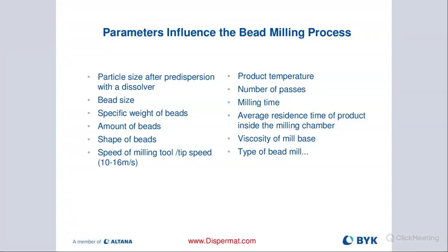So you start out with 1 to 1.2 millimeter beads, mill for an hour, an hour and a half, 2 hours. When you're looking at the results and you see, okay, the last half hour, we're really not getting any more particle size reduction, at that point you want to change out the bead size, go smaller, so that you are targeting the right particle size, and then you run another milling cycle. So that really can add up depending on how small you want to go.